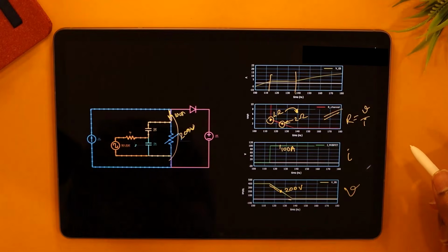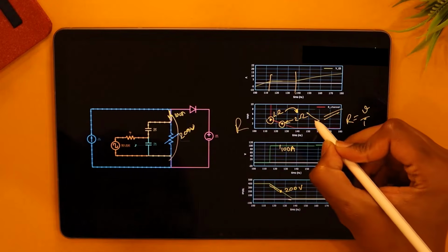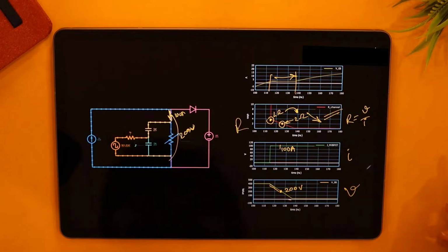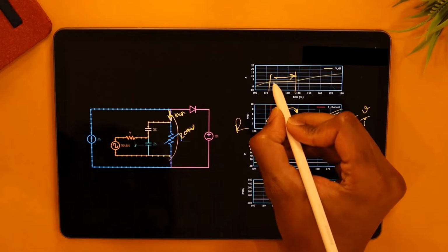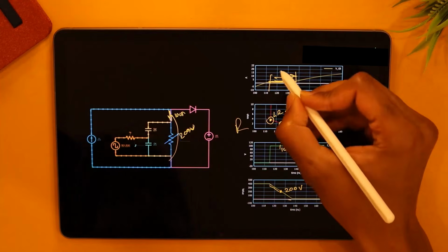And you know what is more staggering? If the resistance of the MOSFET is falling, how come VGS is constant? I mean, VGS, we said right from the beginning, is the control handle on this switch. And I am holding the control handle because of the plateau, it's being held at a constant voltage of 2 volts.